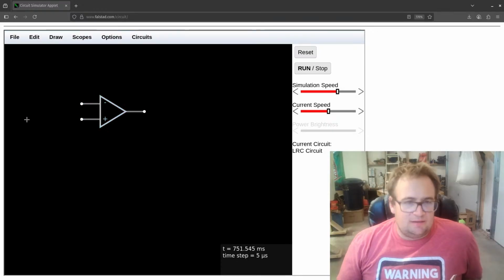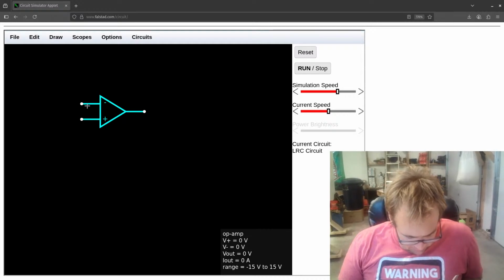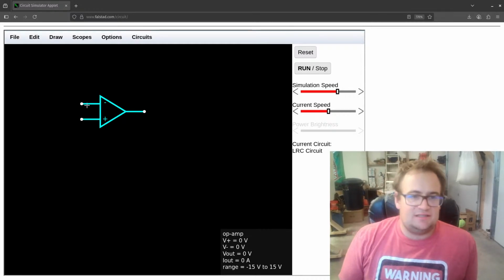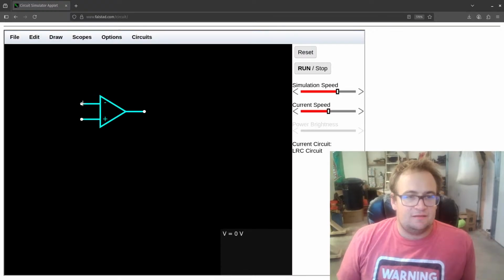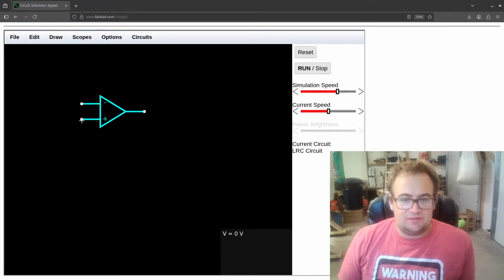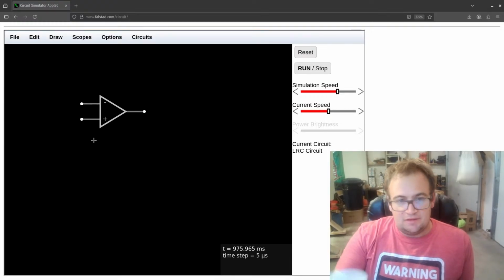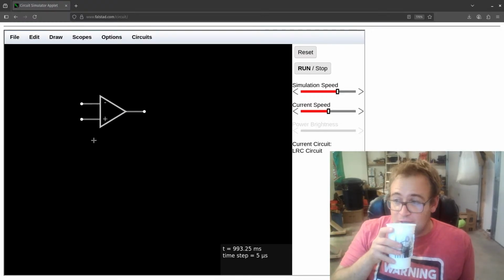And then here's one that is also really important for circuit analysis: there's 0 input offset voltage. So that means there is no difference between these 2 voltages. So if I tie this one to ground, which I will soon, this one will also be at ground. It's called a virtual ground. I'll have a nice drink of my Golden Crush now.